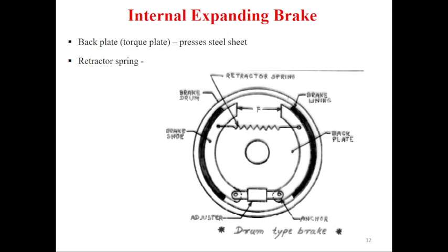When we use the mechanical brake, the crank is moved by the lever as shown here, with the help of the applied force. This applied force expands the brake shoes this way and this way with the help of the brake plate. The expanded brake shoes press on the brake drum, compressing the brake lining.